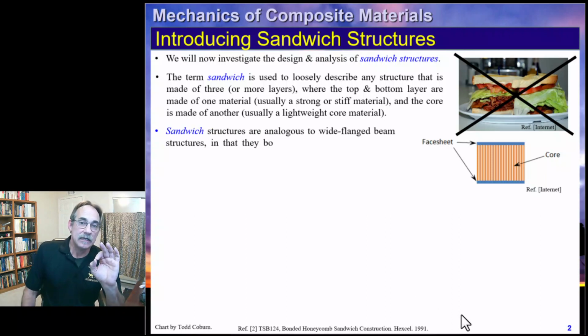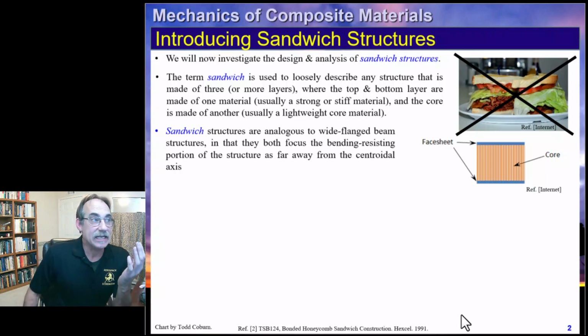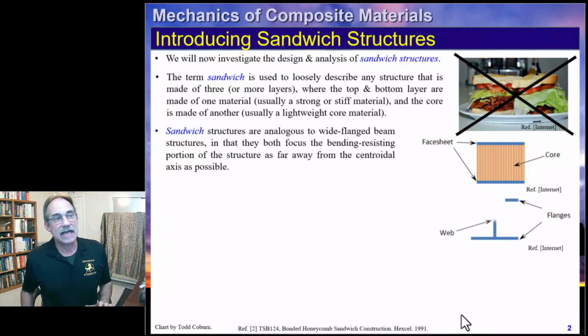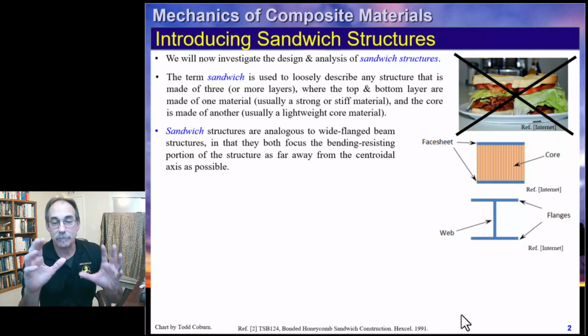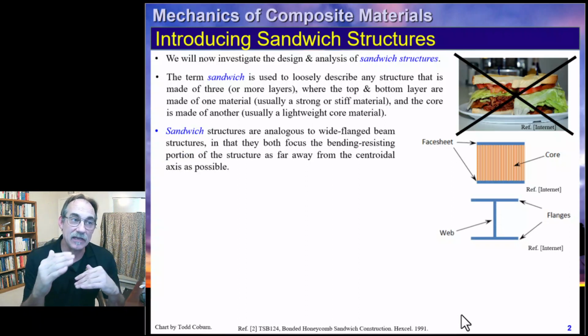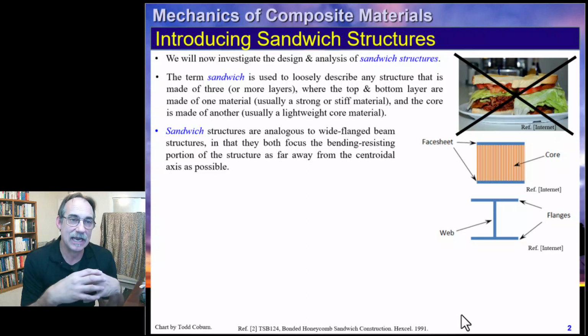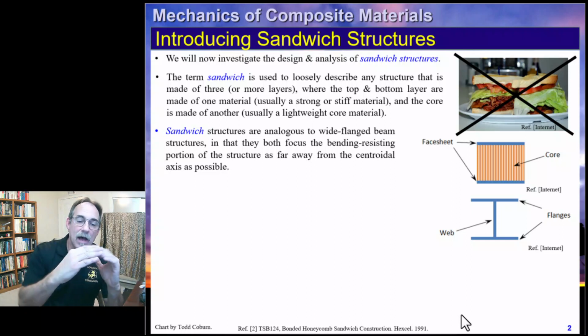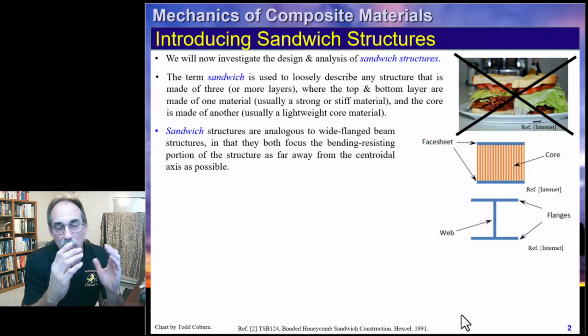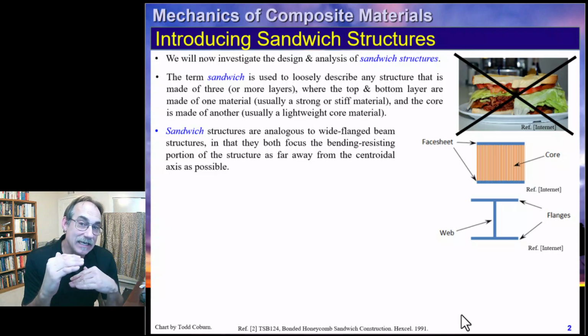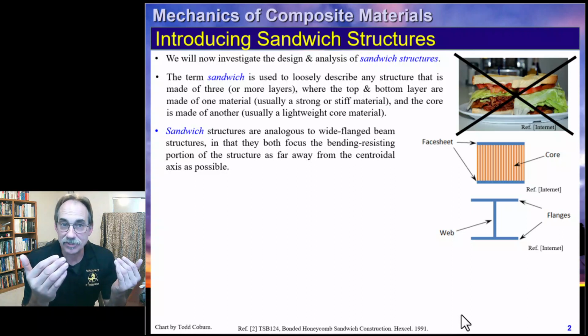We're going to be looking at these ideas and how they play out. One way to bring this back into our intuition is to think of I-beam structures. Remember, from the beginning of our journey in structural mechanics, looking at stress analyses and material behaviors, we've seen that if we can remove area from the cross-section where it's not needed and place it instead where it is needed, we can get a lighter, more efficient structure.